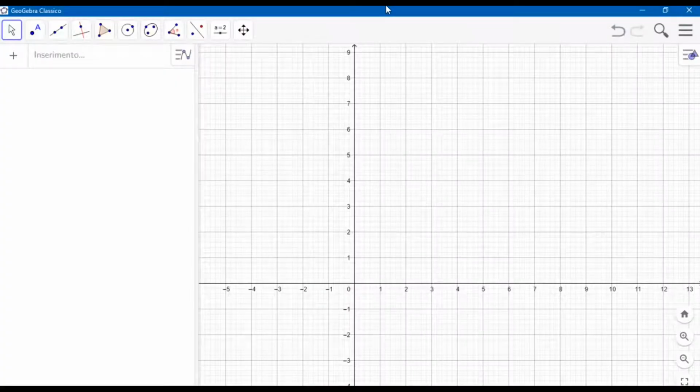Hello guys, welcome to Amazing Engineering, and today in this GeoGebra tutorial we will see how to design a pantograph mechanism applied on a Chebyshev mechanism. As first, let's design the Chebyshev mechanism. Let's set the first fixed rotary joint called A0, whose coordinates are 0, 0.